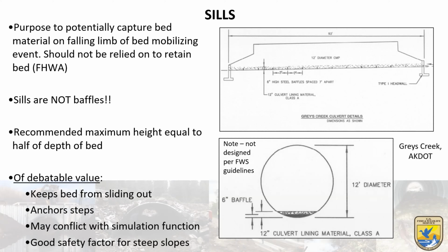It's very hard to put rock in these sand-bedded systems and hope that it stays in place, although it is possible in some ways, but you run the risk of some degradation on the downstream side if you put too hard a material within them. So one of the things to note here is that it definitely is not embedded that far. That would be my only issue with this one.